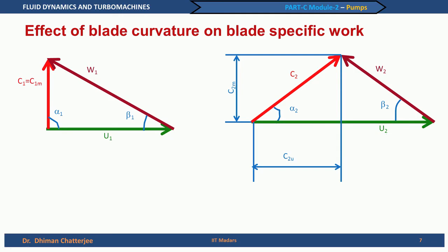In case of pump, the high pressure side is the outlet, and hence we can write W BL infinity. At this point, I am not worried about slip and the losses that we have talked about in the last lecture. We will say we have an idealized Vane congruent flow, and you can recall that we have used the notation BL for blade and infinity for Vane congruent flow, and hence W BL infinity refers to the blade specific work under the Vane congruent flow, that is idealized assumptions.